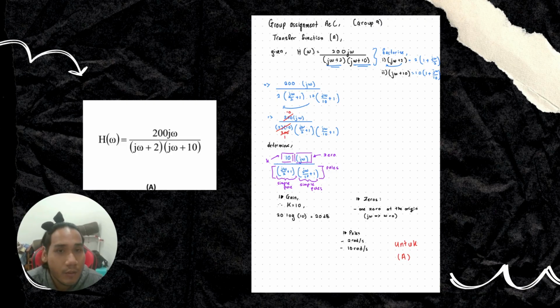constant number. So we can also determine the standard Bode plot form, in which the 10 will be K as the constant number and j omega will be the zero. How do I know this? How do I determine these numbers and also these zeros?